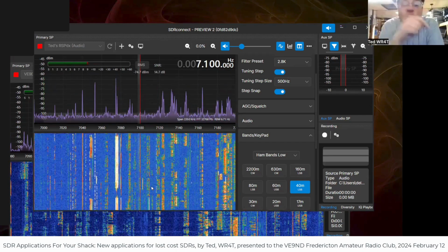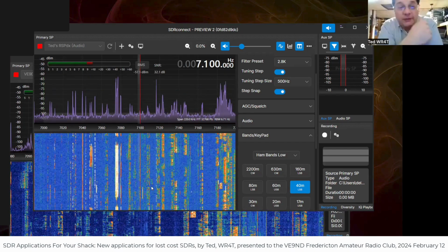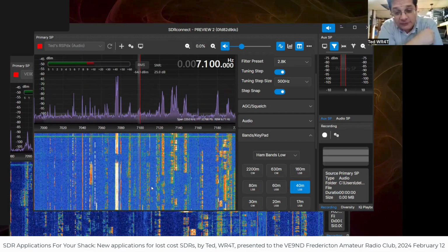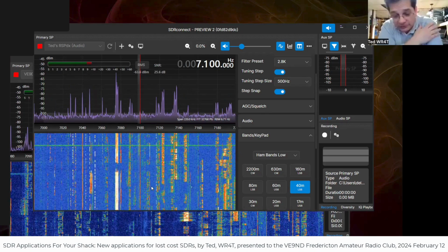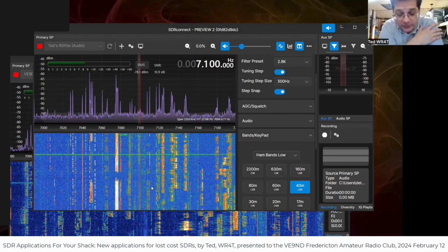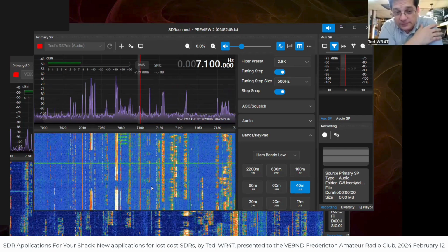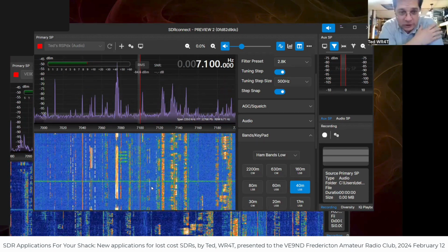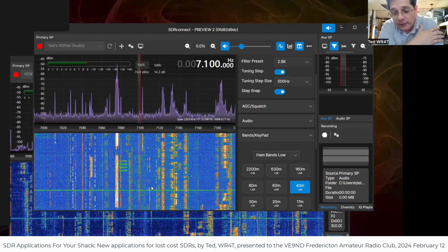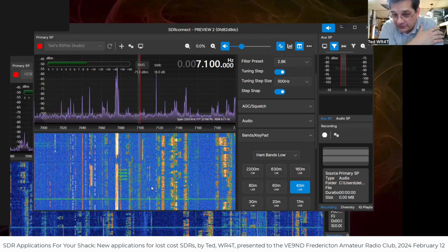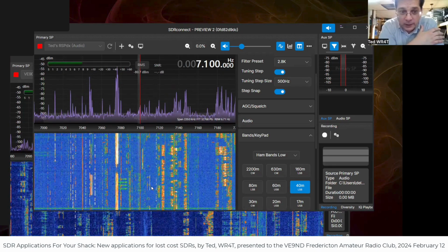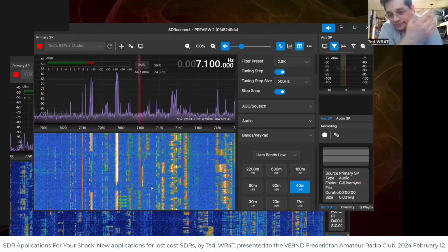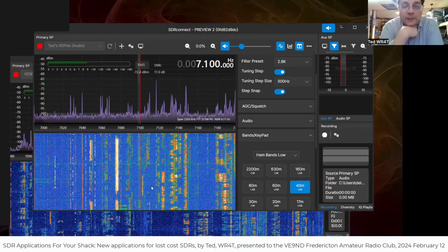I was going to say one difficulty you have if you try to cover the whole HF band at one time is you have to have an antenna that functions across the whole HF band at one time. So you either have to have a multi-ham band antenna like an end-fed half wave that's got a good match, or a lot of people use magnetic loops on the SDRs because they're broadband. And log periodics make reasonable receive antennas. You have to solve that problem, I guess.